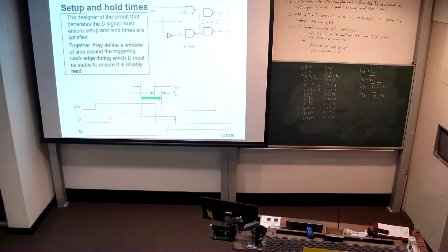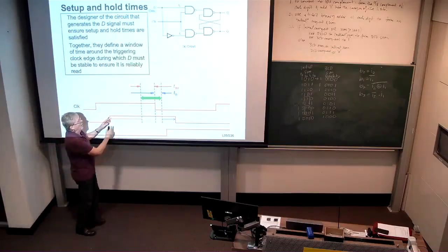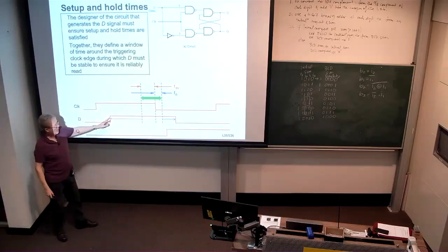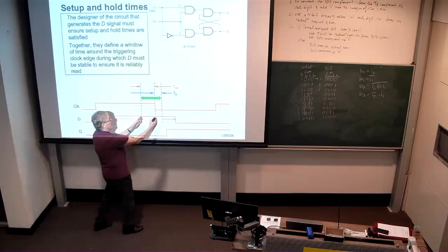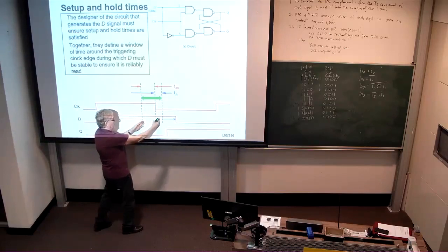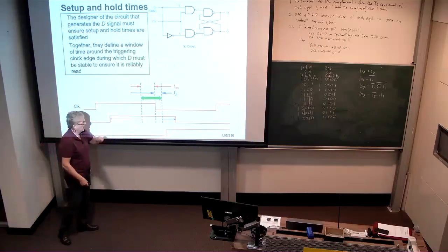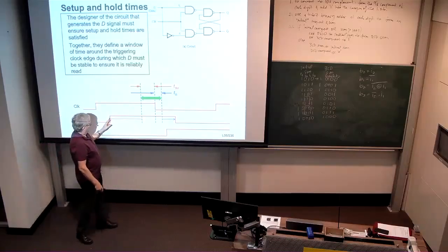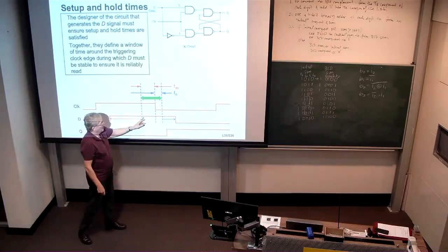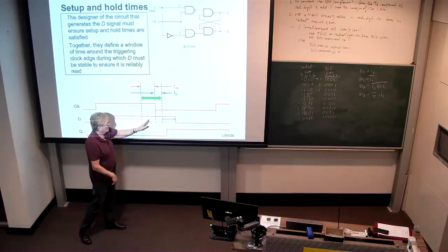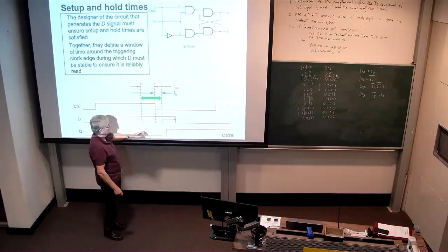latch. So here we see that D goes high well ahead of the clock going low, and therefore this setup time, which is this narrow period prior to the clock going low, is satisfied; we've given it much more time. However, if this D had gone high somewhere inside this period, then that would mean that we may not see the D going high on the output side of that latch, or not see it reliably. It might go metastable, as we'll see in a moment.